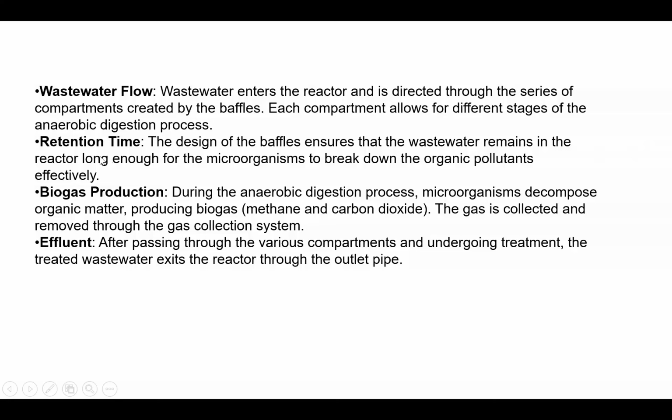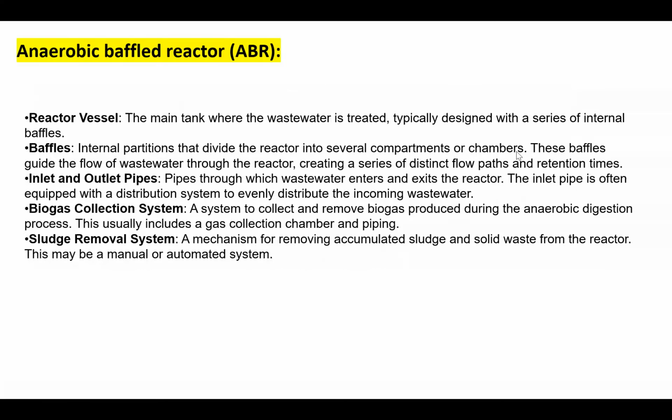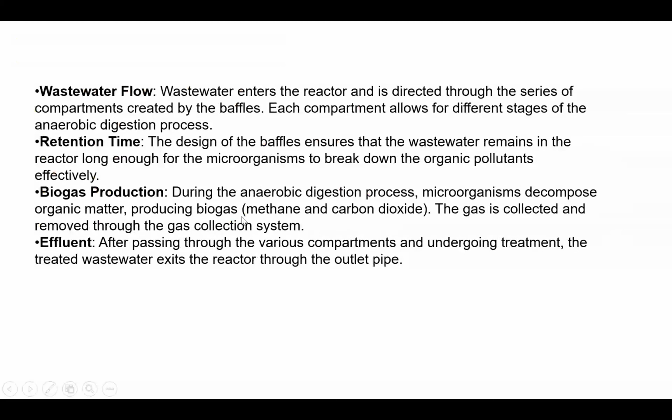Mainly here you see the retention time. The design of the baffles ensures that the wastewater remains in the reactor long enough for the microorganisms to break down the organic pollutants effectively. So they are getting more time. Biogas production: during the anaerobic digestion process, the microorganisms decompose organic matter and produce biogas, as we discussed for the previous chambers.